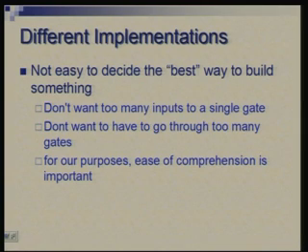If you have a term like A, B, C, that means you are talking of AND of 3. So the question is whether you want to work with 2 input gates, or 2 input and 3 input gates, or whatever your choices are. What is the fan in of a gate you want to limit to?